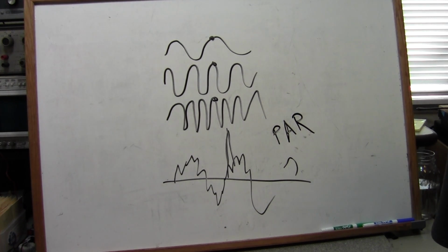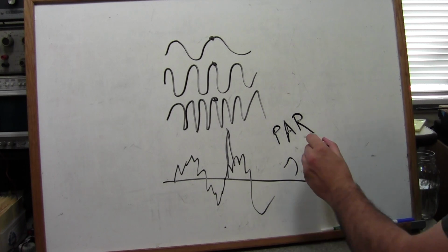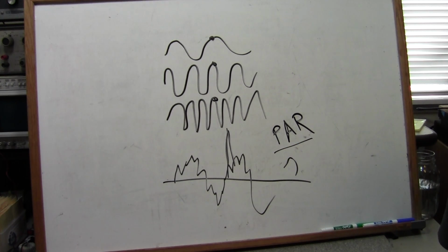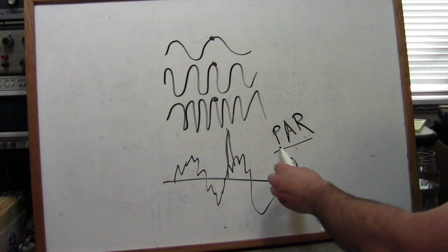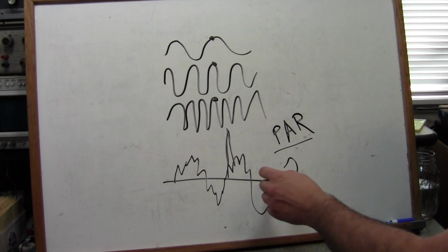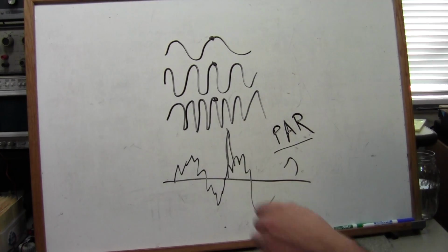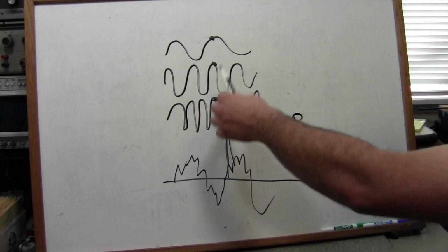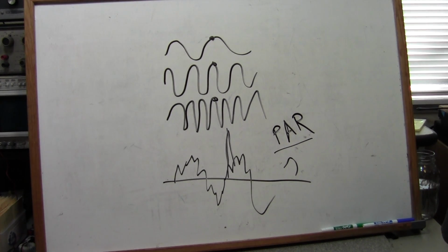The peak to average ratio is important because you have to build your power amplifier to be able to transmit the peak power that you ever have to put out through the modulation. But the effective power that you get to put through the system is only the average. And so if your peak to average ratio is very, very large, you have to have a very powerful PA that most of the time is doing almost nothing. OFDM is very prone to this since you are transmitting multiple different signals at the same time.